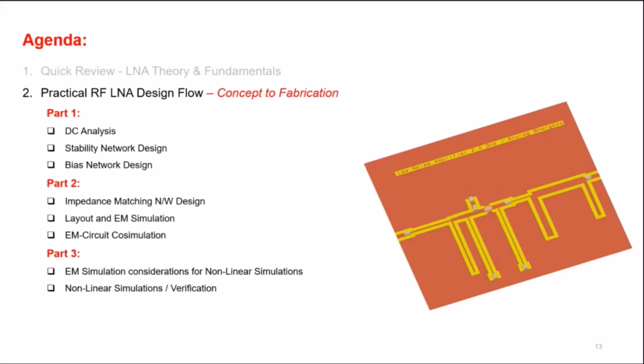From 1 mm, your chip might grow to 1.5 mm. That's why ICs will always give you much higher bandwidth than you can achieve from PCB. But again, the question is, how do you define broadband? There are some clever techniques which may be possible in PCB, but of course, doing multi-octave or even octave bandwidth is not so easy on PCB.